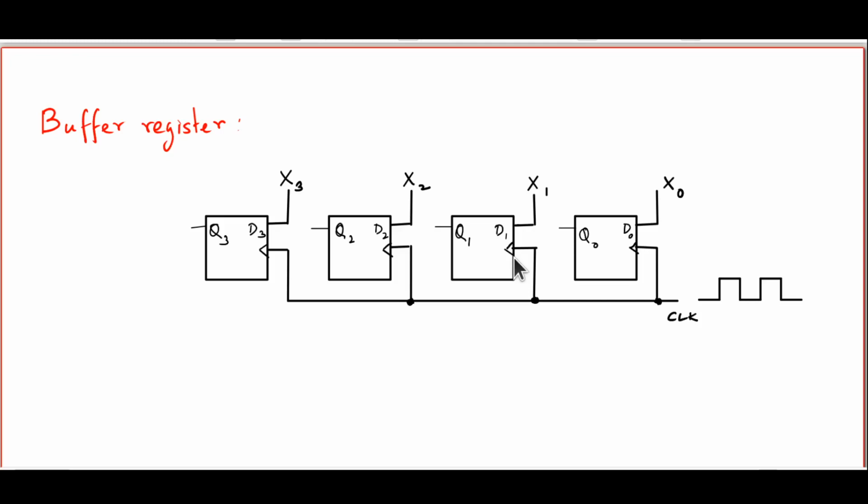And then when the rising edge of the clock goes away, any change that happens in the input nibble in between simply doesn't affect the output. That's a memory condition. Q0, Q1, Q2, Q3 stay unchanged until the next rising clock edge, where again Q0, Q1, Q2, Q3 will respond to the input values. So this is our simplest way of storing a group of bits in a register.